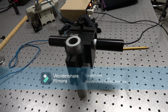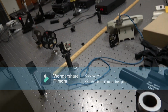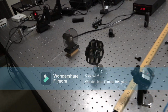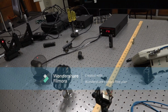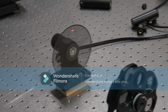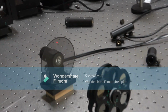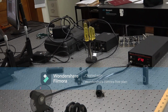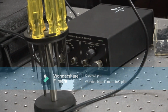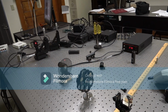And calibrating the photodiode. First we will see minimizing the background room light. In this we need two components, the chopping wheel and the lock-in amplifier. The chopping wheel is an optical device that periodically interrupts or modulates the light beam, creating a pulsating light signal. And the lock-in amplifier is an electronic instrument that detects and amplifies signals with a specific frequency, effectively filtering out steady background light.